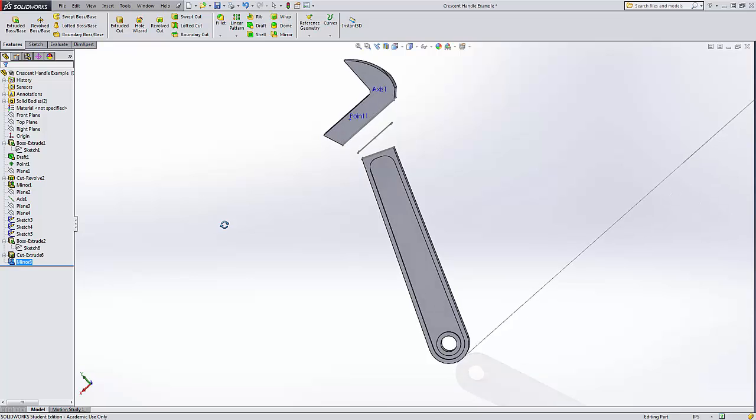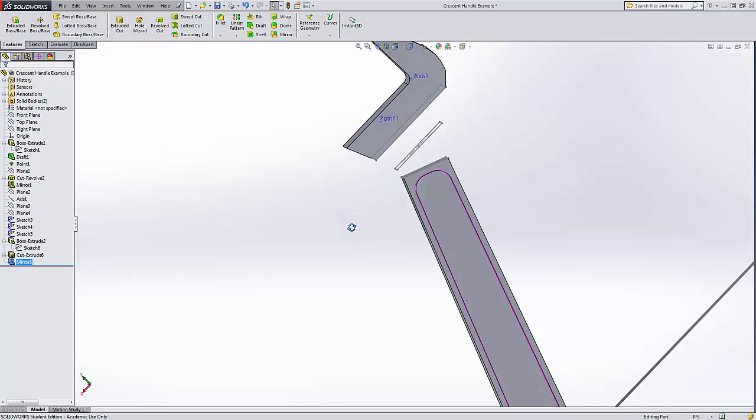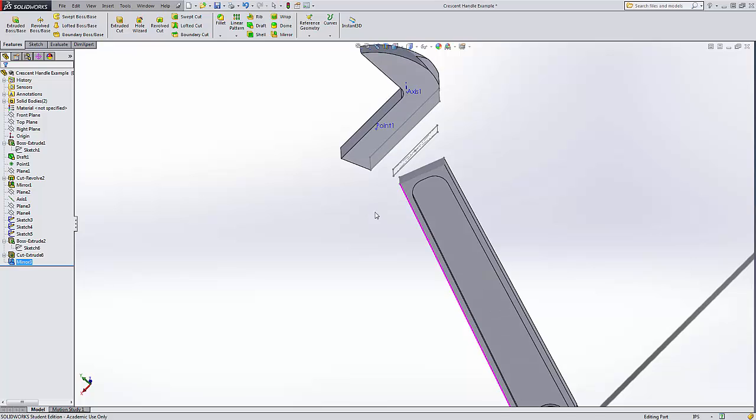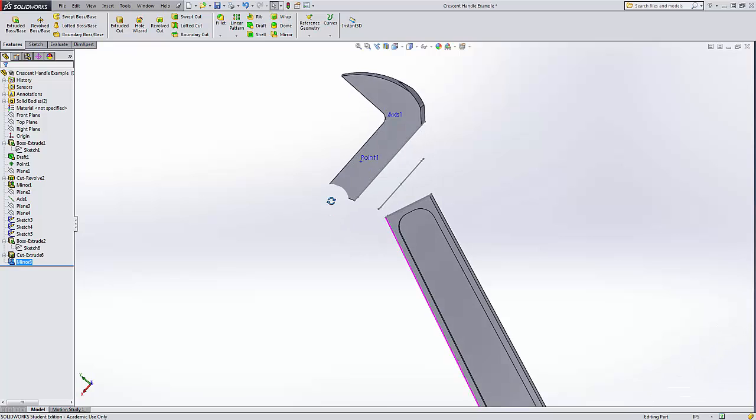All right. Now we can connect these two with the loft. I had to do these sketches and these planes so that we could at least get to this sketch, and then this sketch gave us this surface and everything else down here, and so now we can do the loft.